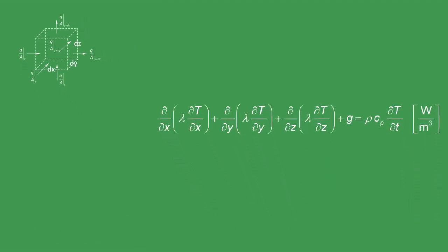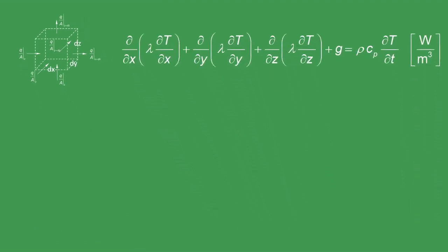As you can see, the heat diffusion equation is an energy balance inside a solid to which we have applied Fourier's law to evaluate conduction fluxes. Therefore, when you apply the heat diffusion equation, remember that the point of departure has been this energy balance.